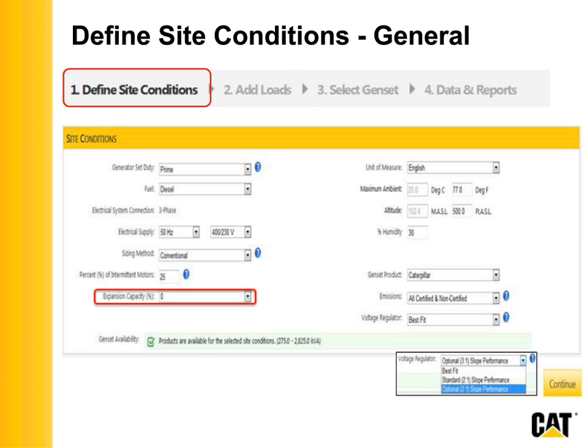It's not just straight linear loads, it's not just straight motor loads. We allow up to 30% capacity, and it's important to understand that if your load scenario sizes a genset that's lightly loaded or prone to wet stacking, loaded at less than 30% capacity, this feature will not take effect. We're not going to cause your genset to be even more lightly loaded.